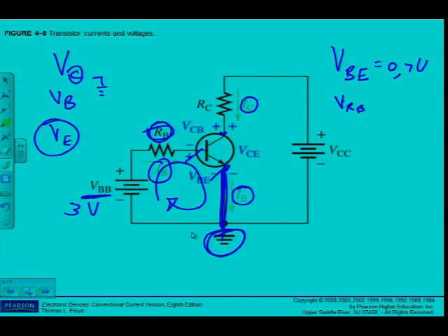Alright, so VB and VBE will be the same, because VB is measured with reference to ground, from base to ground. We've seen that is approximately 0.7 volts. But if I measure VBE, which is, I put the red lead, remember we read from left to right, so VBE, so the red lead goes onto the base, the black lead goes onto the emitter. What will the value be?